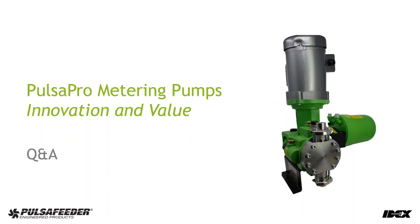Okay, thank you, Jeff. We had another one from LinkedIn, and it says, I understand, so this might just be a clarification question, Jeff. I understand that the bypass condition window can be used to check if the HPV, hydraulic bypass valve, is operating each stroke, which will reduce the pump flow rate. Kindly confirm. Yeah, I read that beforehand.